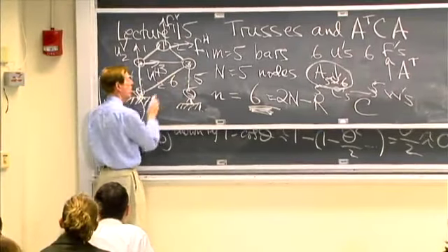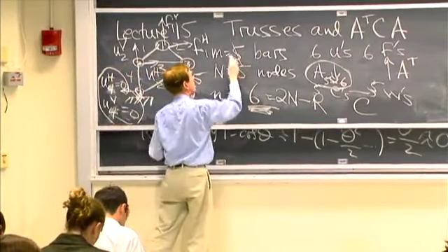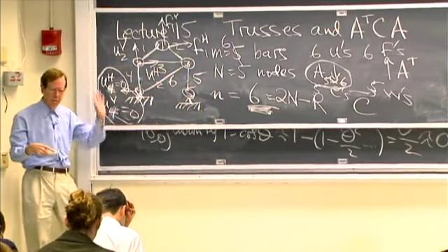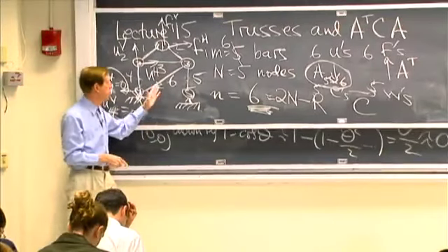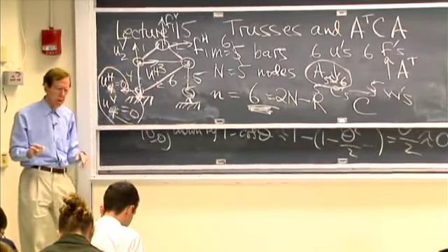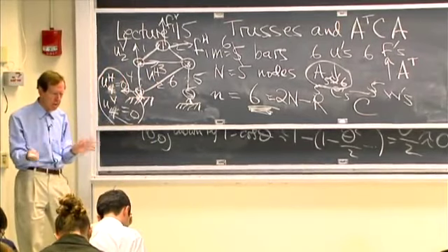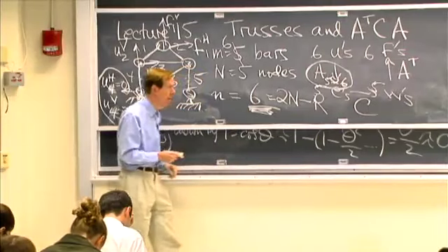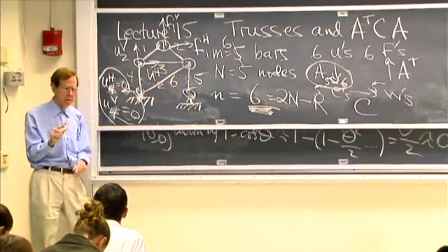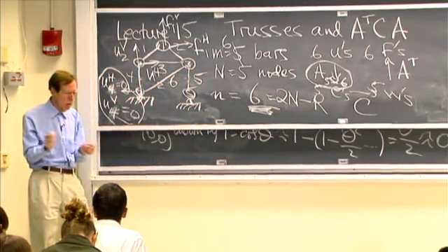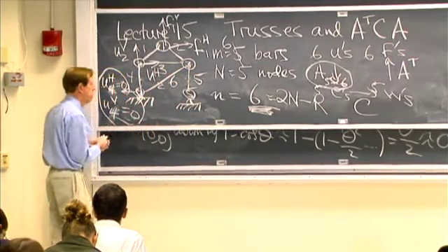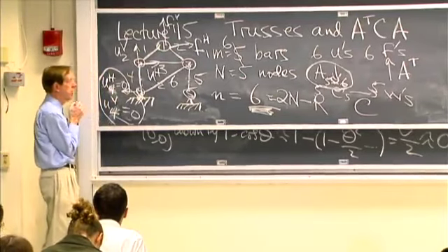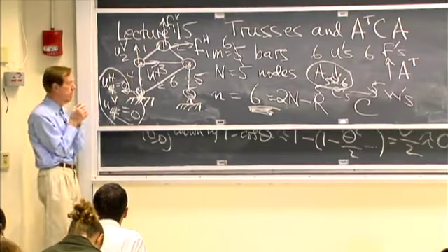We've now got 6 bars. So M is now up to 6. The matrix A is 6 by 6 now, whatever that matrix may be. We have 6 bars, 6 displacements. We do have a 6 by 6 matrix, and we can hope that it's not singular. We can hope it's invertible. We can hope that that mechanism is killed, and you see it is killed. That truss is now stable. No mechanism there, right?